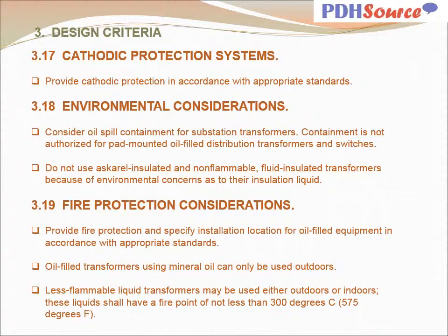Provide fire protection and specify installation location for oil-filled equipment in accordance with appropriate standards. Oil-filled transformers using mineral oil can only be used outdoors. Less flammable liquid transformers may be used either outdoors or indoors. These liquids should have a fire point of not less than 575 degrees Fahrenheit.